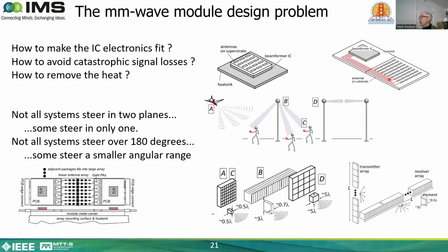One way of addressing that problem is to move the antenna array from being above the integrated circuits to being beside them and running interconnects between them. There are two problems. One problem is the high frequency losses on those interconnects, and the other is just physically routing them as the array becomes larger. So this approach can work for perhaps a 16-element array, but is not viable for larger arrays. This two-dimensional array problem at half wavelength pitch is a fundamental high-frequency design challenge that is being addressed by many research groups in the IMS community.